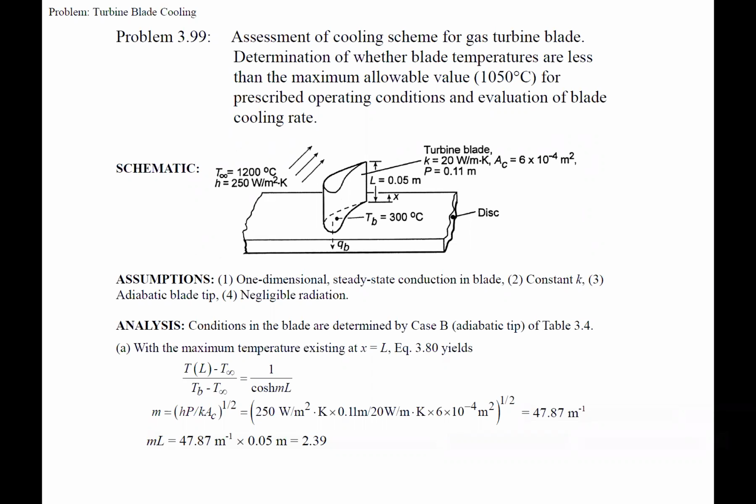With a couple more things plotted on here, but we have our blade, right? They give us this base temperature of 300. They give us the turbine blade, which is this. They have this perimeter given to us. Maybe they went in CAD and grabbed the perimeter and cross-sectional area. And we have Inconel, so we have the thermal conductivity of it.